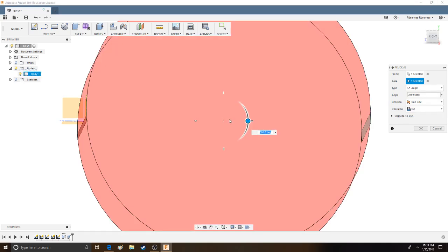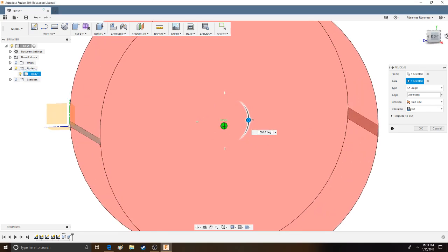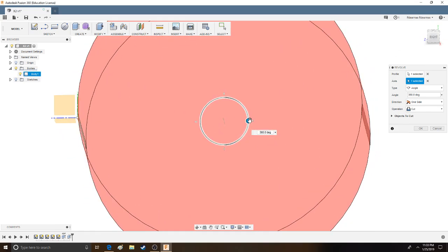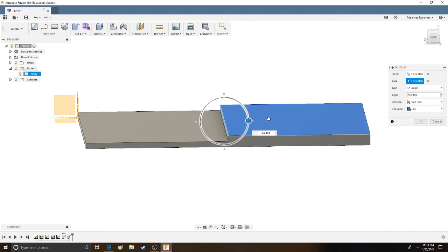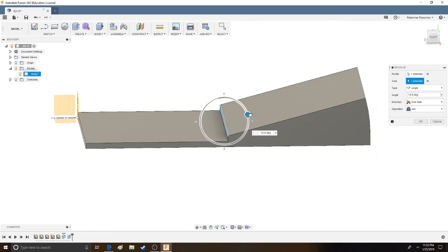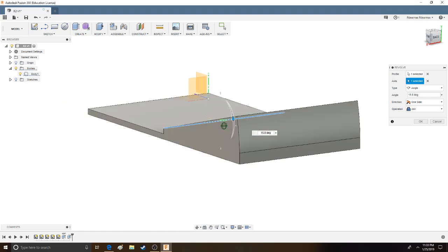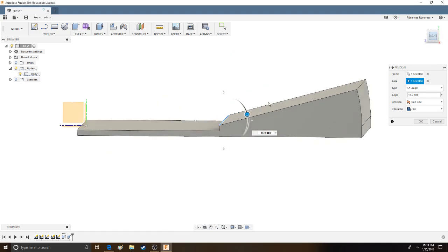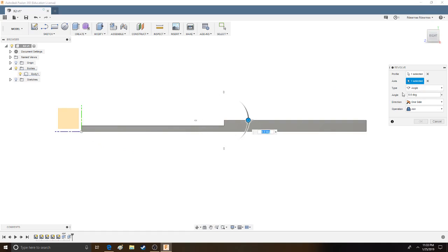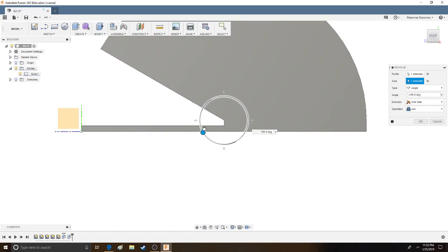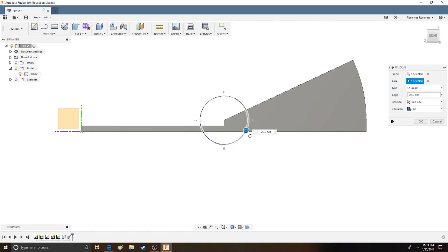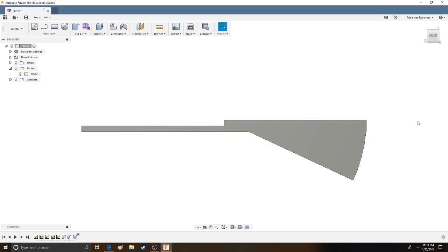So for this, we're going to be doing this, which, yeah, stuff like this happens a lot while using the revolve tool, but don't be alarmed. Simply go back and select this, and so you turn something that was originally just a flat surface into a very, very curved surface. The original was just flat like this, but using revolve, you can set it as an angle and go in the direction you want it to go. You can either go all the way in this direction, or just half. For this, we're going to leave it at 25 degrees. Feel free to change it up, do whatever you want with it. But for now, we're going to keep it as join and click OK.